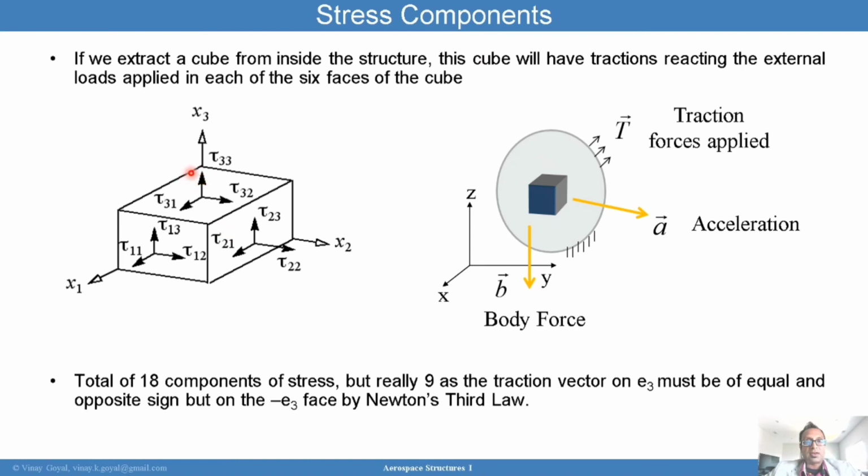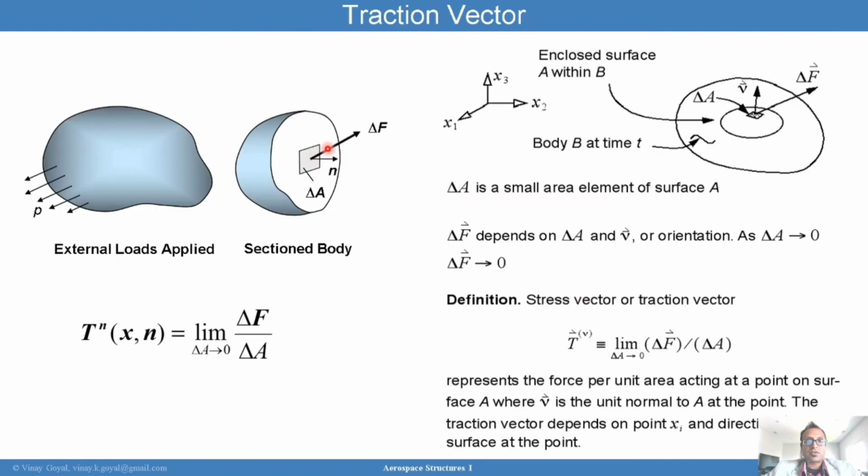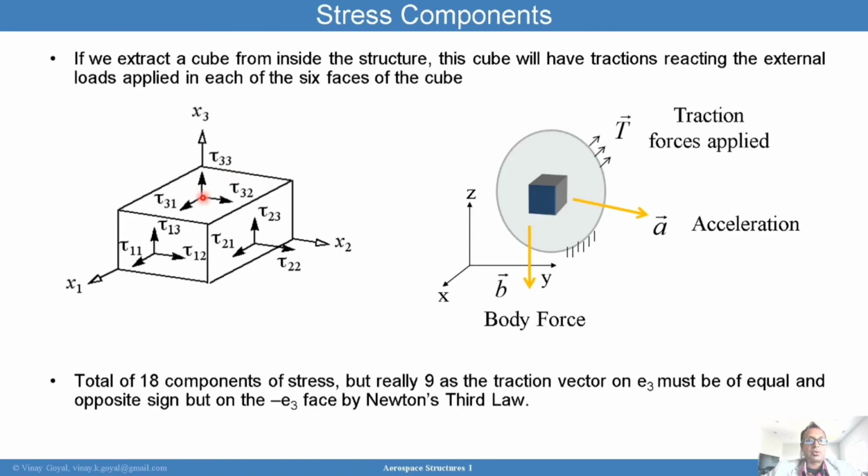So let's look now at what's going on with this face. This face is from the inside of the structure, and I expect a traction force like this one, this traction force acting arbitrarily on this face. I also have another traction force acting on this face, another traction force acting on this face. I have traction forces acting on 6 of these faces, and when I look at that traction force, I can decompose that traction force into 3 different directions.